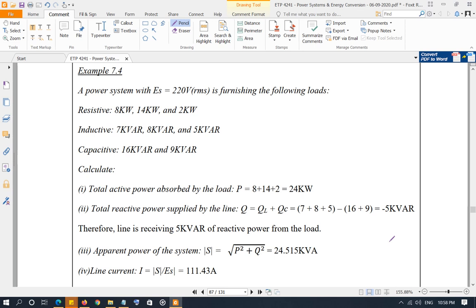That means that actually the source is receiving the power instead of power going out of the source, reactive power, that is. The source is receiving some of the power because the capacitors are producing more power than what is required by the loads that are connected in parallel, reactive power we are talking about. So the reactive power is coming back to the source, which goes basically in energizing the field of the generators that are producing the power for the line.